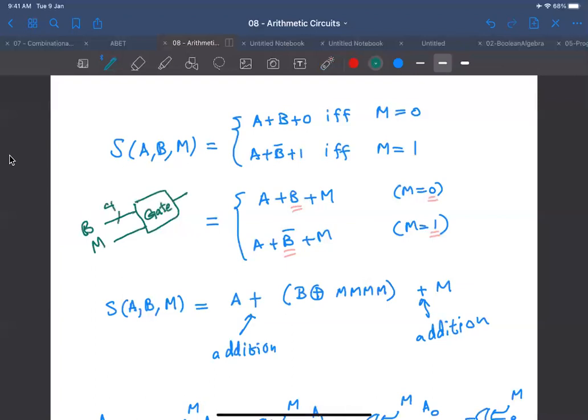So let me take only one bit of B, because M is 1 bit. And we would like to output B0 complement when M is 1, and B0 when M is 0. What is this gate? We learned a gate like this before. Well, if you do remember, if I have an XOR gate and I XOR B0 with 0, what do I get?